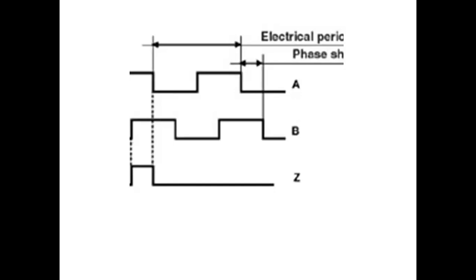The light passing through the slits is transmitted or blocked accordingly. The light is converted into an electrical current in the detector elements corresponding to each slit, and the output is two square waves. The two slits are positioned so that the phase difference between the square wave outputs is 1/4 pitch. This type of encoder outputs a pulse string in response to the amount of rotational displacement of the shaft.